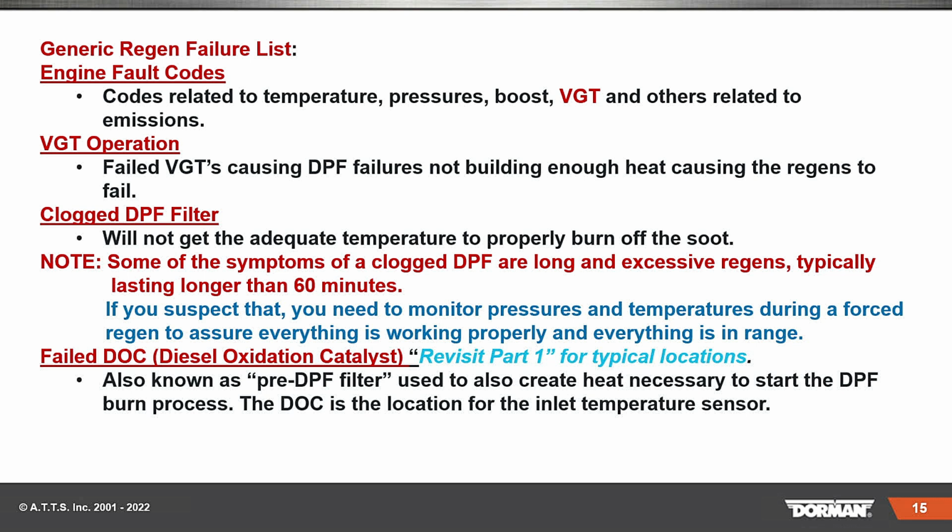So once you start breaking in, you might have to restart the process. It's like you trying to interrupt the doctor working on your heart, I guess is the best way to look at it. But anyway, that's a good debatable question, absolutely. So again, generic regen failure list: engine fault codes, codes related to temperature, pressure, boost, VGT, and others related to emissions.